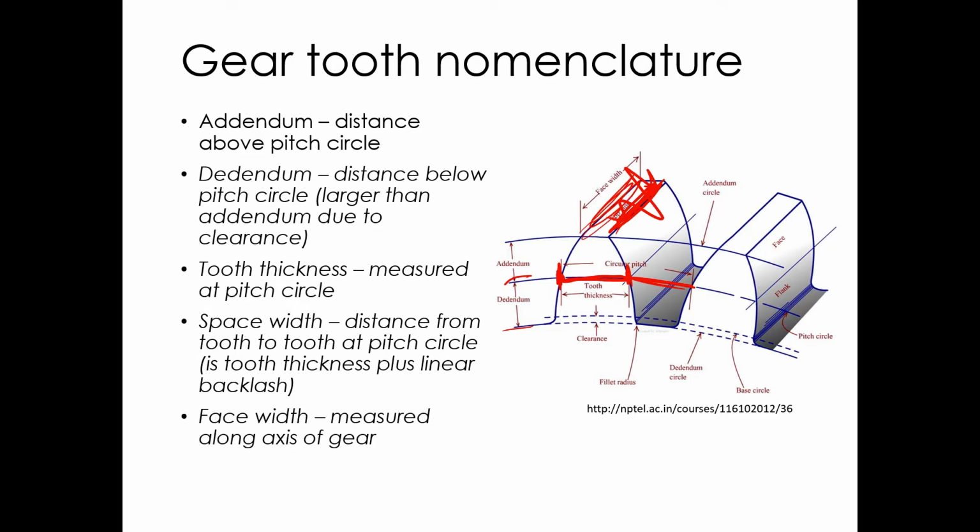Anything else? Yeah, so down here you can see there's a clearance. This has just been offset down an amount, and then a fillet put down here. You could just do this as a whole fillet if you want to as well. It doesn't really matter. There's just clearance so that the other gear's teeth don't dig into that area. And in some gears it's required, in some it's not.